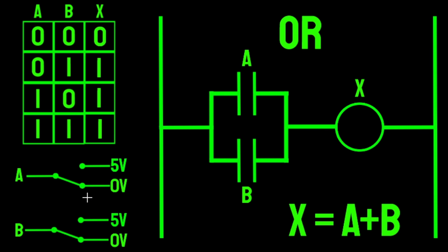So you can see now, with both of our inputs pulled low, both of our normally open contacts will be de-energized, and so it's impossible for the signal to get through to the output in either branch. If we energize only our A input, then our A contact will energize as well and become closed. This way, we can see it doesn't matter what B is, because we have a direct path through to the output via A's closed contact.